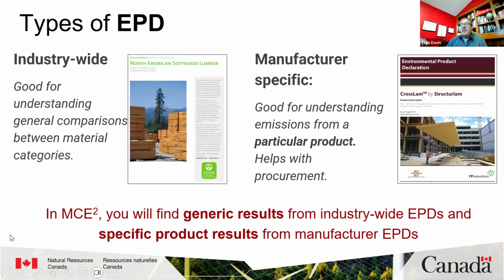And with these generic results, we have to be very mindful of that. Where it may be helpful in the early stages, once we get into design development and we start to select specific products, go to those product specific EPDs and you'll get more accurate estimates of your embodied carbon.